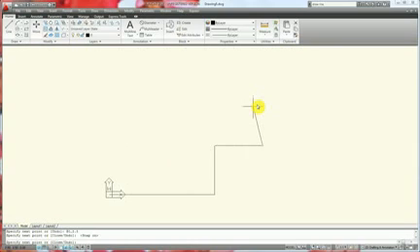And now I'm going to enter a polar coordinate, which is going to be @3, then the arrow, be sure it's a left pointing arrow, 90, which means a radius of 3 and an angle of 90. Press enter.